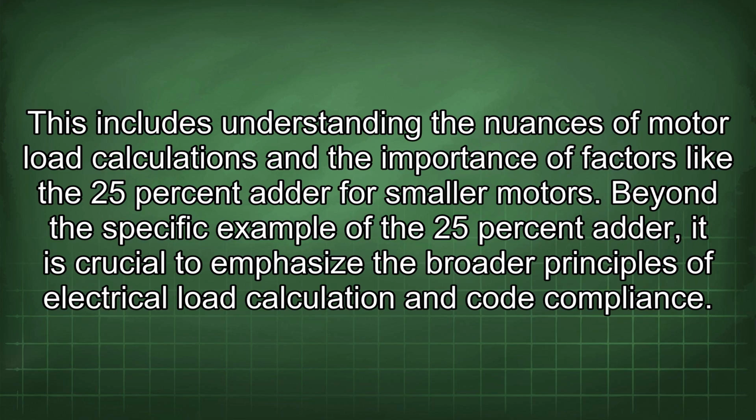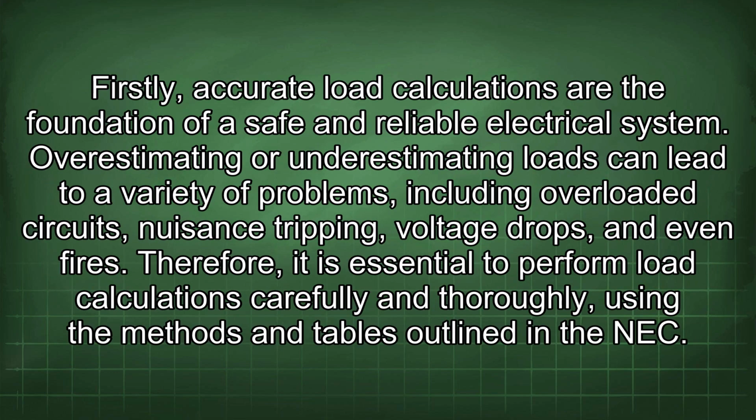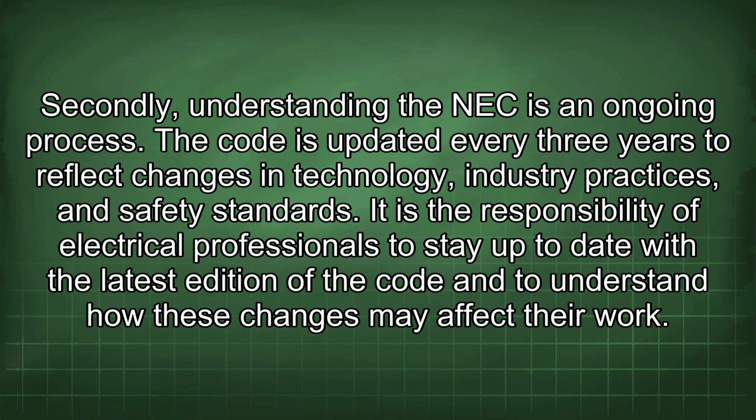calculation and code compliance. Firstly, accurate load calculations are the foundation of a safe and reliable electrical system. Overestimating or underestimating loads can lead to a variety of problems, including overloaded circuits, nuisance tripping, voltage drops, and even fires. Therefore, it is essential to perform load calculations carefully and thoroughly, using the methods and tables outlined in the NEC.